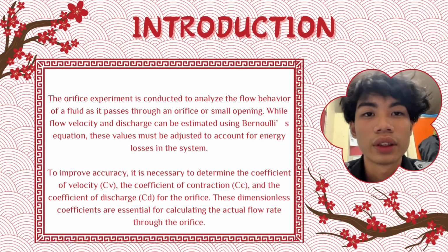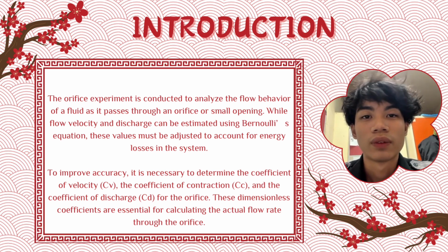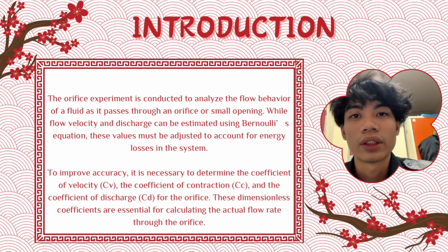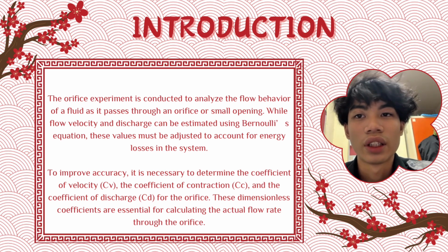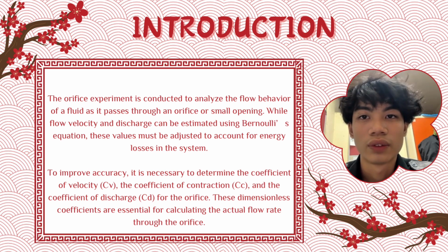Okay, for the introduction, the orifice experiment is conducted to analyze the flow behavior of a fluid as it passes through an orifice or small opening. While flow velocity and discharge can be estimated using Bernoulli's equation, these values must be adjusted to account for energy losses in the system. To improve accuracy, it is necessary to determine the coefficient of velocity CV, the coefficient of contraction CC, and the coefficient of discharge CD for the orifice.